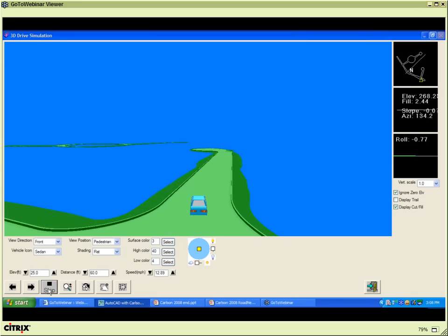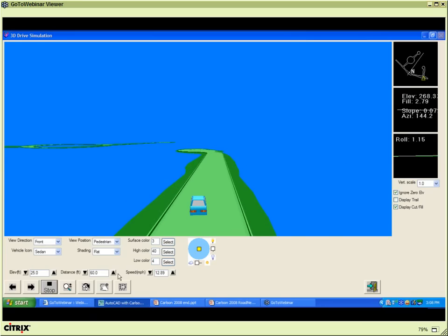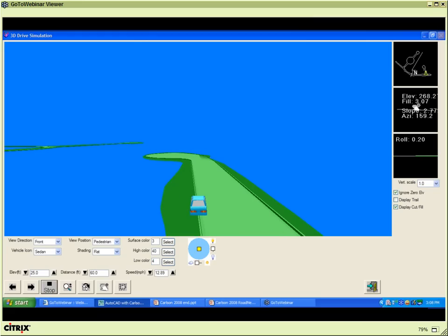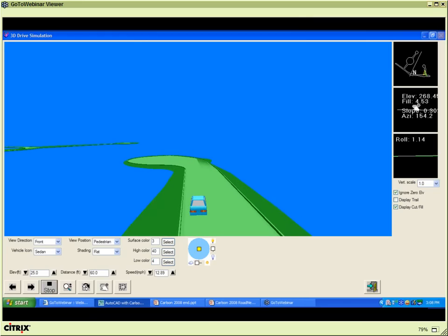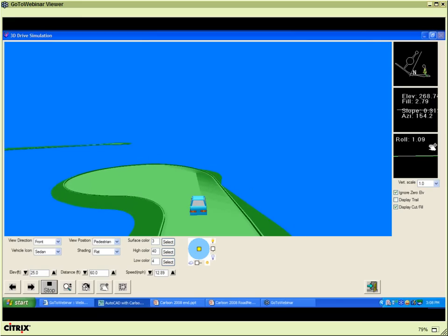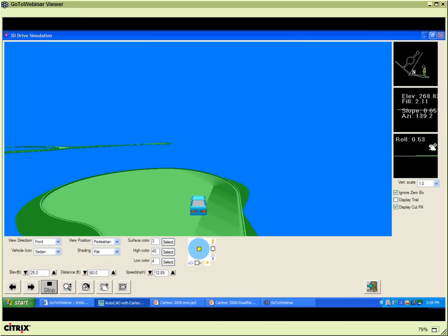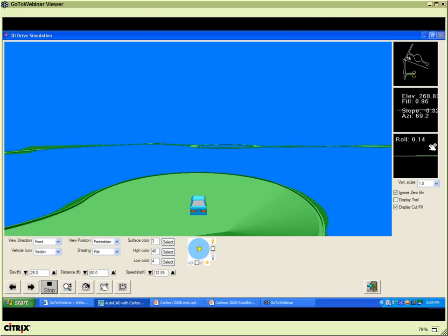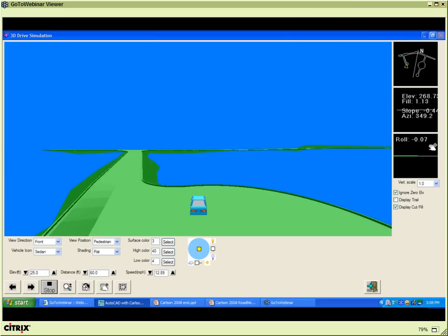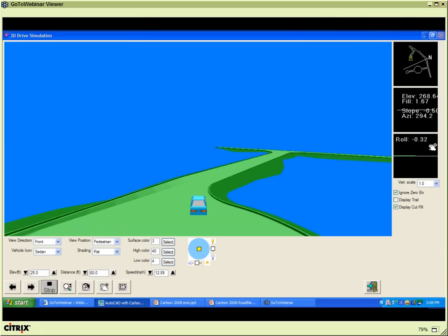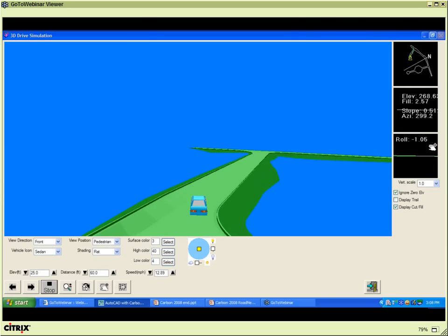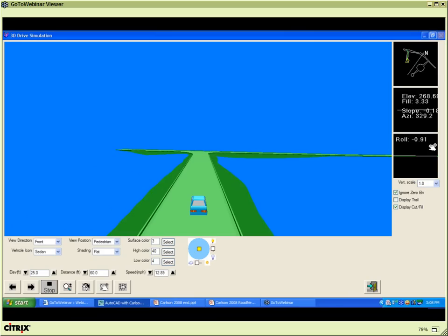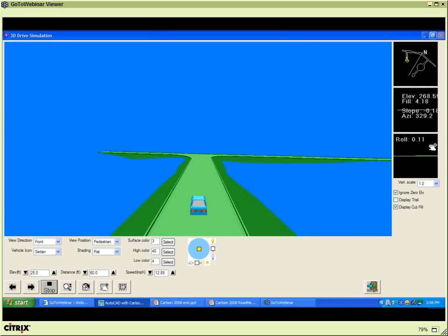Now, while I'm driving through here, if you look up at the top right corner, it says elevation. I'm in fill, and it gives me the depth of fill that I'm in. It also gives me my slope. It gives me my rollover here. And so that's why I picked both of my surfaces, is so that I can see whether I'm in fill or cut, that information. We can also in the software show you, which I'll do here in a few minutes, is that you can also have it colored in with blue and red, showing your cut and fills with your triangles.